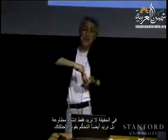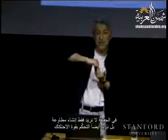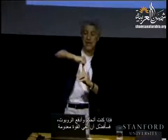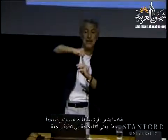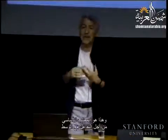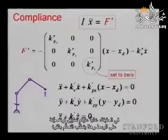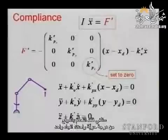But actually what we want to do is not only to create a compliance, we want to control the force, the contact force. So if I'm pushing the robot, I would like it to maintain 0 force. So when it feels there is any force, it moves away, which means we need feedback. We need a force sensor. And this is really the requirement in order to interact with the environment. Most of the time, actually, you want to apply a specific force on the environment, and that requires control of forces. Here we just removed the position control from 1 degree of freedom, one direction.